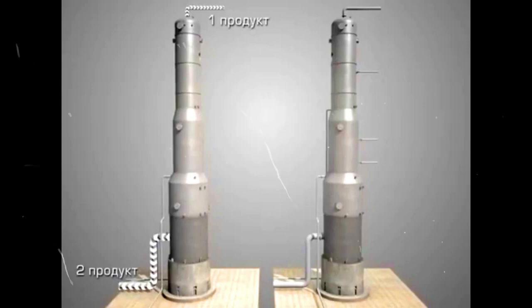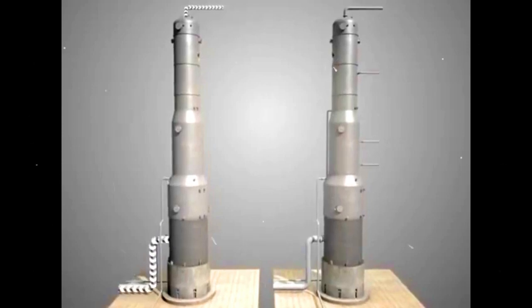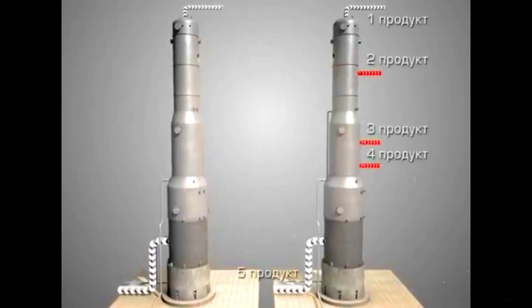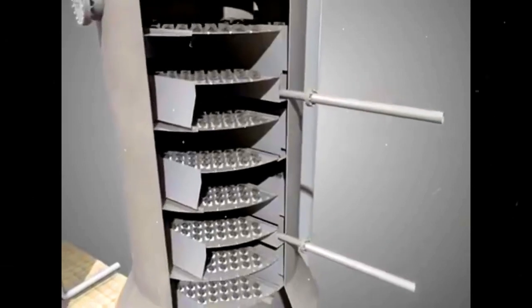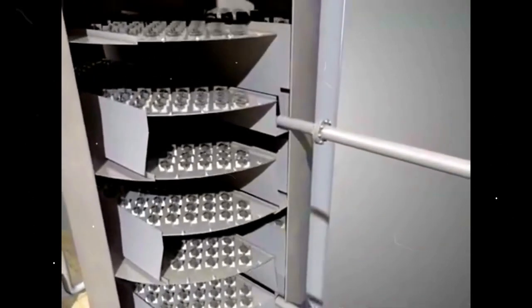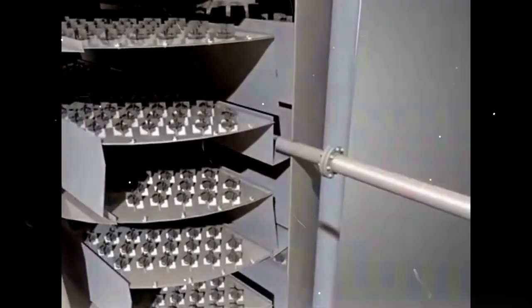The two features that should be maximized in packed beds are the open area, which is the average percent of the cross-sectional area of the column not blocked by the packing, and hence available for the flow of vapor and liquid,